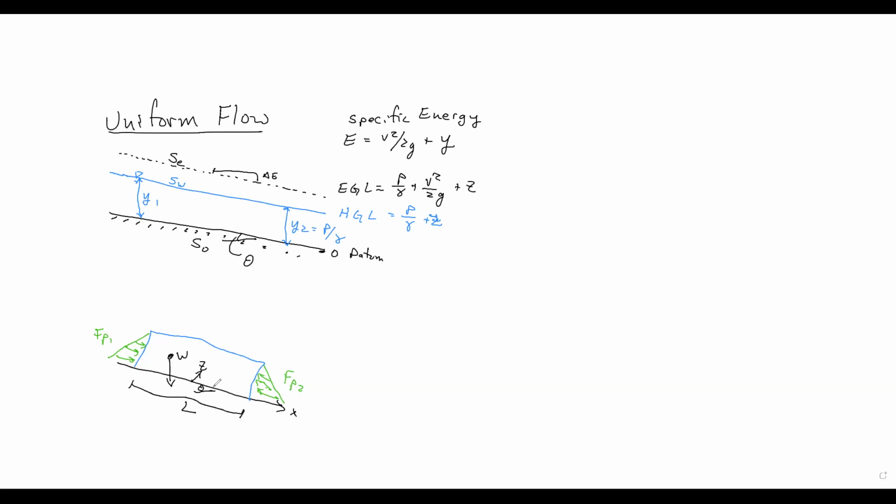And what other forces do you think are acting on this water? So we're talking about the pressure. Is there anything else happening in this control volume? Yeah, there's going to be some friction, right? We always have to think about friction. So we'll call that force of friction. And it's acting against the water, the water kind of moving across the bed.